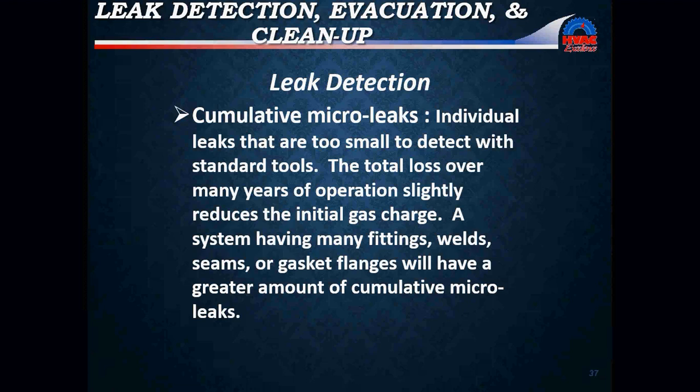Look for oil staining. Look for oil staining and an accumulation of dirt in areas of the coils and vibration eliminators. Look around the compressor. If you see something like that, there's a chance that there's a leak there. Oil spotting is the technician's first quick check for leaks, but it will not always be reliable for some of